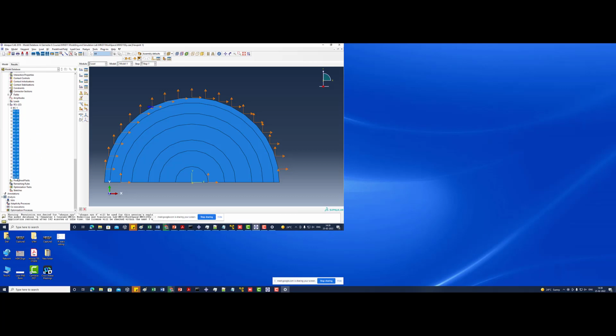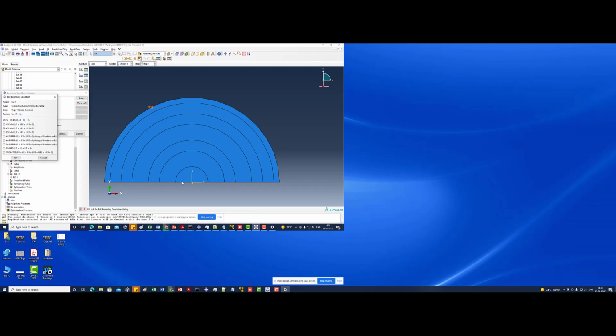So we delete all these things. Okay, still there is one. One boundary condition which we have to keep is that this section has to be y symmetric. So the ligament has to be y symmetric because we are modeling half of the circle. So we have to select not this, we have to select this half. So this has to be partitioned.